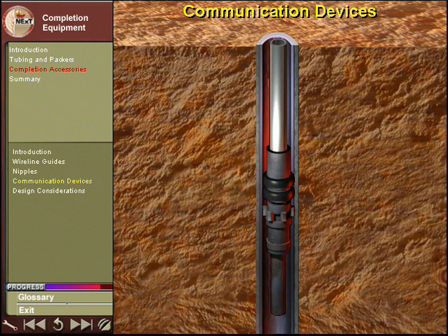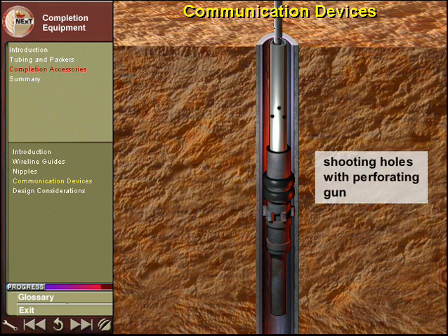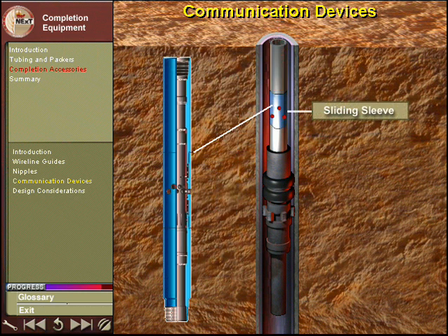While it is often best to seal off the tubing casing annulus with a packer, you sometimes need to let the fluid flow in this space. For example, you might need to circulate fluids. In this case, you can shoot holes in the tubing, but this leads to problems later if the holes can't be isolated. The most common solution to this problem is a sliding sleeve. A sliding sleeve can be opened to allow circulation, and then closed to once again seal off the annulus from the tubing. Slickline or coiled tubing can be used to convey the shifting tool that opens or closes the sliding sleeve.